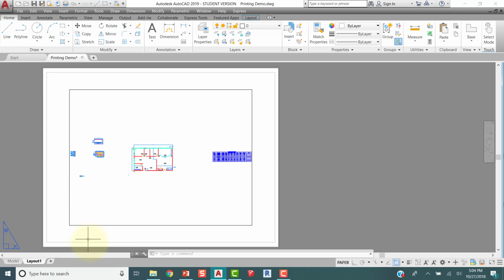The one thing we can see is that everything that is in the drawing is showing. So it's all been squished down to fit onto this piece of paper, which does happen to be an 8.5 by 11-inch piece of paper because that is what my current printer supports. We want to print on a large piece of paper, but at home I can't do that. But I can set up a PDF that will allow me to create a layout that's the right size, and then I can either print the PDF or I can print my regular drawing using that print setup on a printer that actually has those print settings.